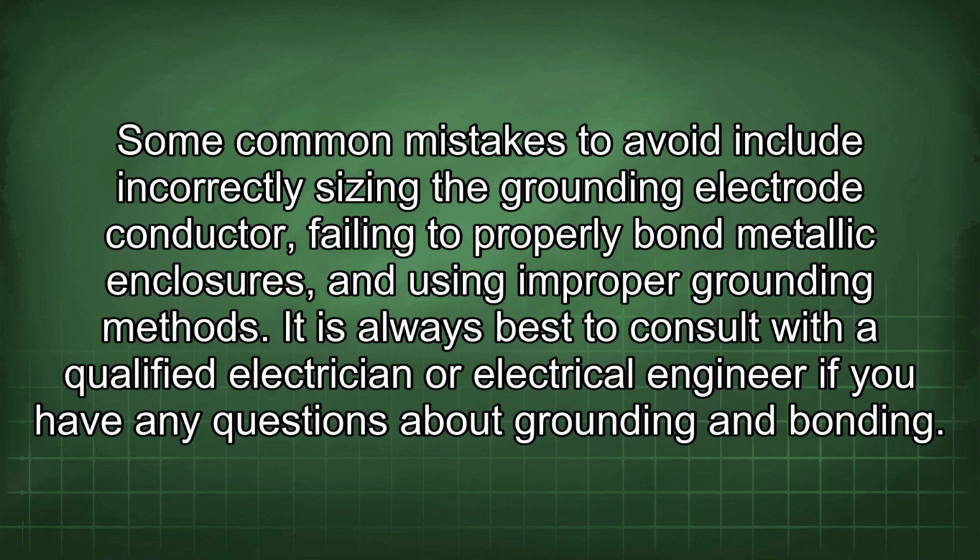Some common mistakes to avoid include incorrectly sizing the grounding electrode conductor, failing to properly bond metallic enclosures, and using improper grounding methods. It is always best to consult with a qualified electrician or electrical engineer if you have any questions about grounding and bonding.